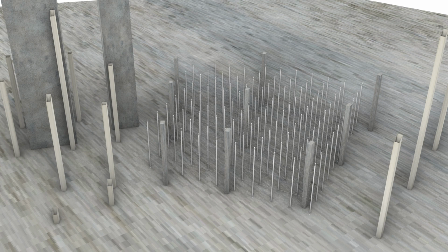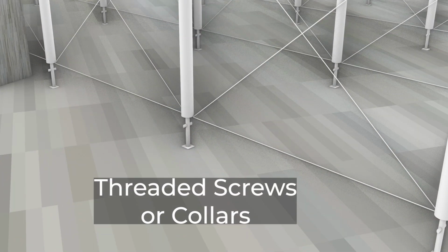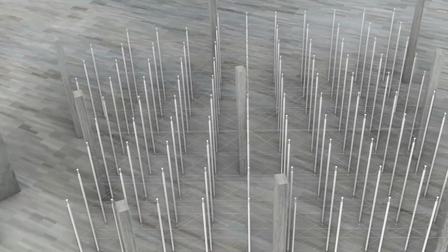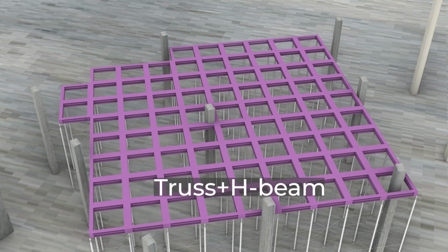Steel pipes used in the temporary shoring system often include height adjusting mechanisms. These feature thread screws or collars that enable precise height control, even by a few millimeters. Such adjustability ensures a level formwork surface and helps maintain consistent slab thickness across the entire pour. For wider spans and heavier load zones, trusses and H-beams were added to distribute weights and support the formwork above.